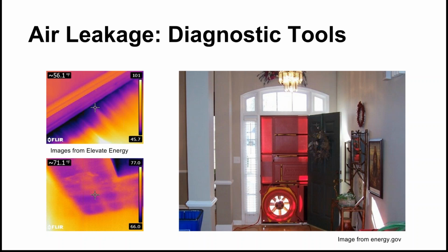And then another quantitative approach, but it's a little hand-wavy, is looking at the approximate leakage area of the house in square inches, which is a conversion from the leakage in cubic feet per minute. So that tells you, oh, I'm looking for maybe 12 square inches of leaks that you can find in a variety of places. You can find them in baseboards, in the attic, in the basement, just all over the place. And I'll talk about that a little more in this next slide.